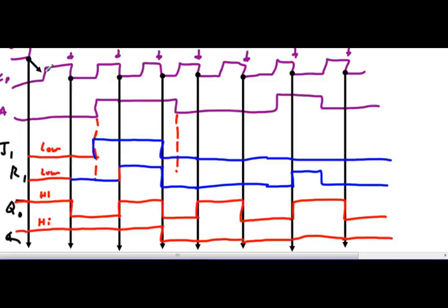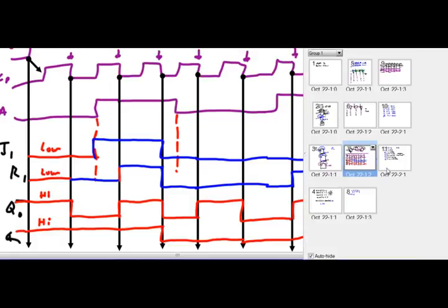So here's my clock, boom, boom, boom, going up and down, up and down. I'm dividing by 2 already on the first output. So the clock has to go down twice in order for me to get back up once. So that's why the divide by 2, the 2 to the 0 spot coming out, ends up dividing by 2. Or words to that effect.